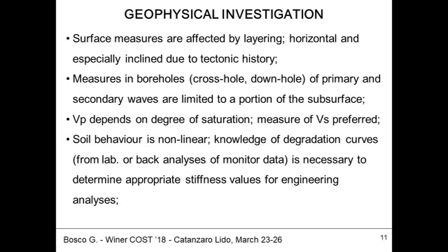In the case of geophysical investigation, the limitations are the interpretation of surface wave measurements due to layering, especially when layering is not horizontal as we are used to, but is inclined due to tectonic stresses, or parts of the subsoil are displaced, dislodged due to past tectonic movements.